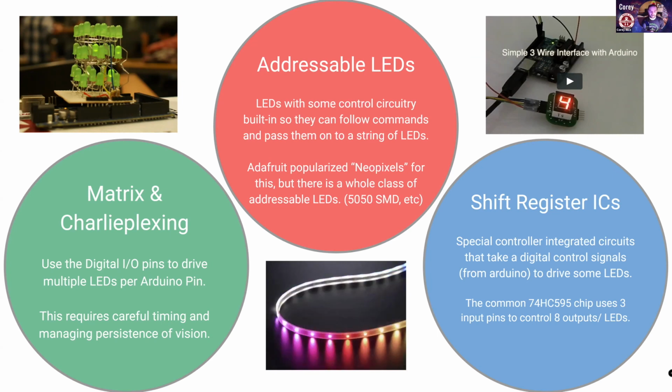So if you can balance those 2 configurations just right, you can get, I think the example we're going to see in a second is that I controlled 6 LEDs with just 3 pins. So if you play with time and connections just right, you can optimize how many LEDs you drive with a smaller number of pins. And then another one that's relatively easy is Adafruit's Neopixels.